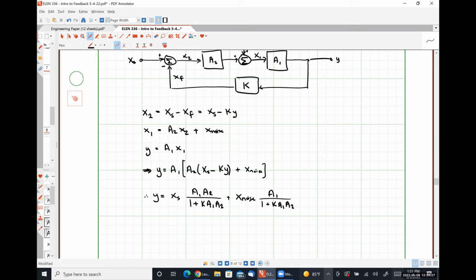In this closed loop system with negative feedback, our signal is scaled by a factor that is A2 times larger than what our noise is scaled by, meaning that our signal to noise ratio is boosted by a factor of A2. This is how negative feedback is utilized to increase the noise performance of a system.